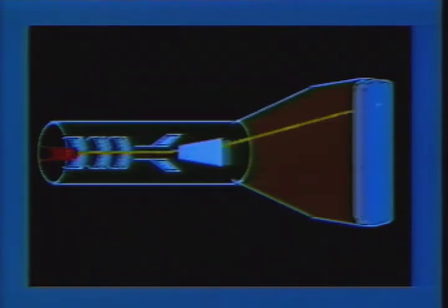The 2467 CRT supplies more electrons with an electron multiplier just behind the phosphor. This type of electron multiplier is called a microchannel plate. The plate is a glass honeycomb structure of very small glass tubing fused together. Coatings are applied to this assembly, and inside the CRT, it's supplied with voltage. Each tube is an electron multiplier.